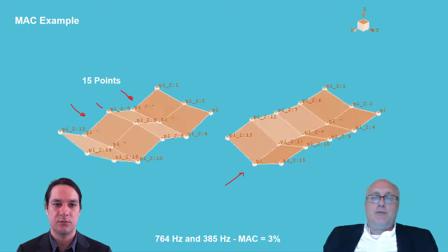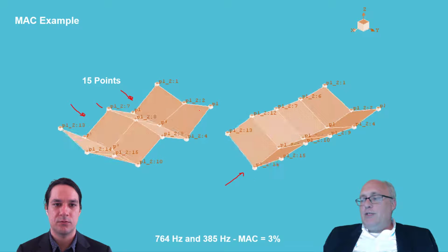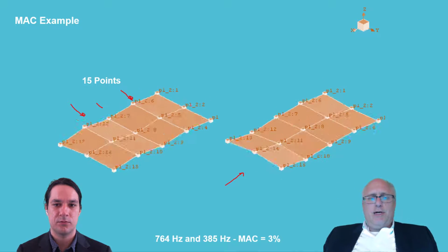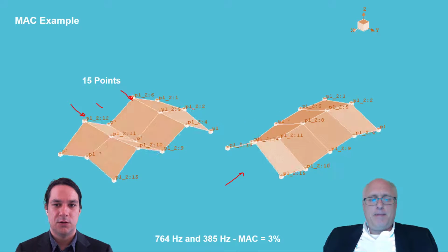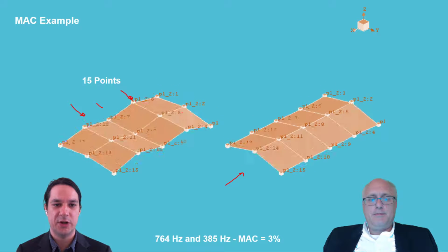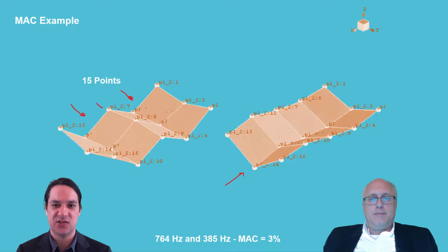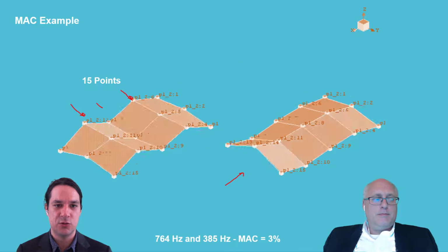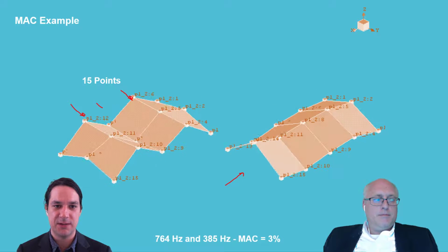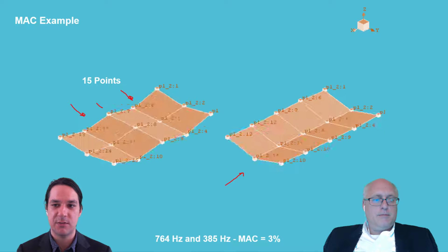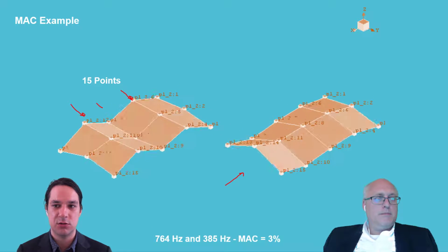and I think we're going to do some simulation for test here, we want to know if we're going to measure enough points. How do you think we can go about doing that, Nick? Well, Pete, I'm really not too sure. We need, I guess, some way of maybe trying to choose a subset of points, do a modal analysis, and then look at the MAC, and maybe we could add in more points if the MAC is not sufficient.